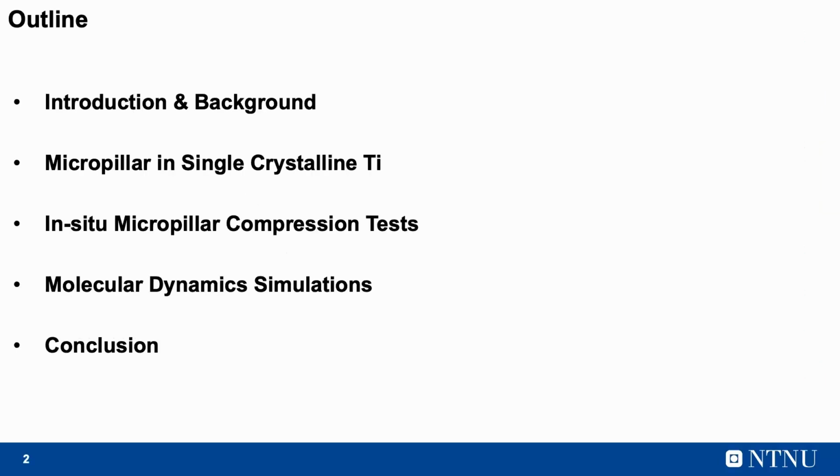So let me start with the outline. I would like to first introduce the titanium microstructure and also the hydrogen uptake into this titanium microstructure. To understand the effect of hydrogen on these titanium-based metals, we performed a series of micropillar compression tests. First I will show the orientation and geometry of these micropillars, and then I will go through the in situ micropillar compression tests. Lastly, there will be molecular dynamics simulations in the same orientation for these tests.